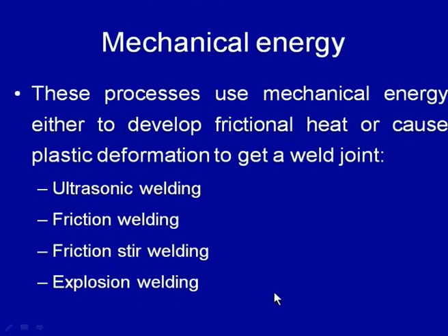While in case of explosion welding, high kinetic energy is imparted to one of the members to be joined using an explosive, and the movable plate is guided and allowed to move in a very controlled way, so that it hits the other member in very controlled positions at a particular angle, so that the metallic continuity between the members to be joined is obtained primarily through mechanical interlocking.